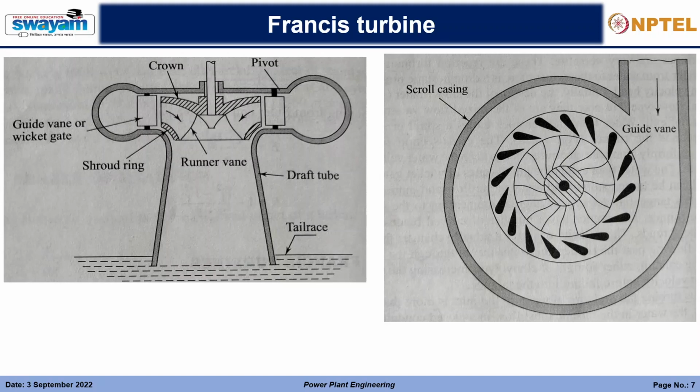In the Pelton wheel, the water jet strikes tangentially to the wheel, and that is why it imparts force, impulsing upon the buckets. As a result, it rotates the buckets. So it is a pure impulse turbine. But Francis turbines are actually impulse reaction turbines. Kaplan turbine also. Again, Francis and Kaplan are a little bit different based on the flow direction.